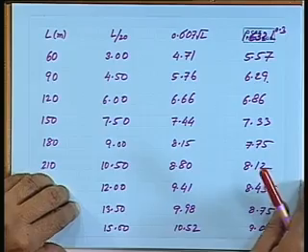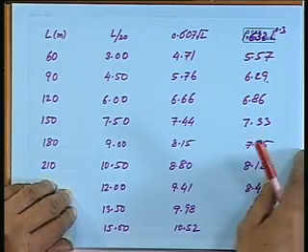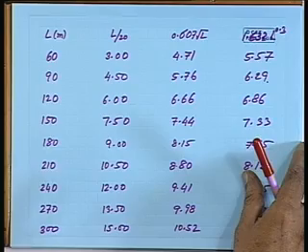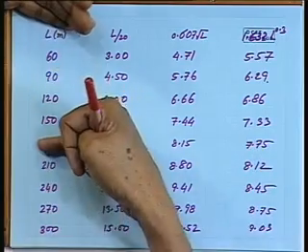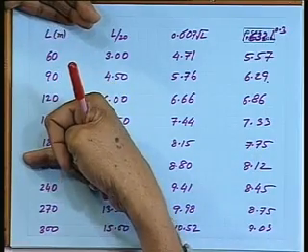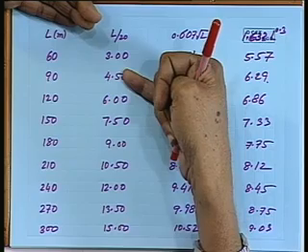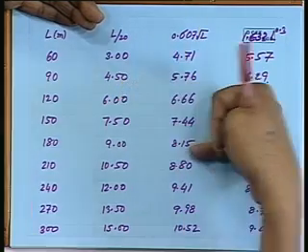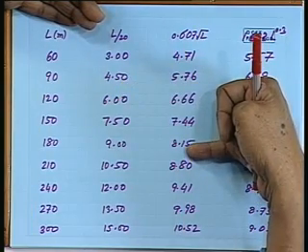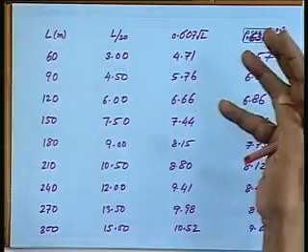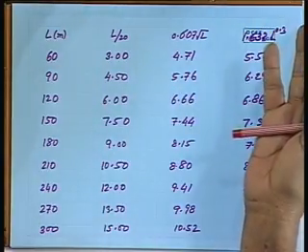And therefore, somewhere or the other one has to make some sort of realistic assumption, and this helps in finding out what should be the wave height. So if the vessel is up to this, yes, wave height should be taken as L by 20, no doubt about it. But beyond that, why should you unnecessarily strain your calculation or strain your vessel when it is not going to be strained that much?